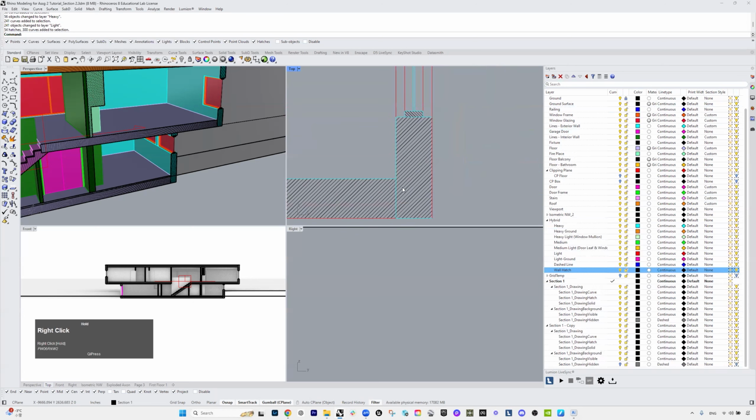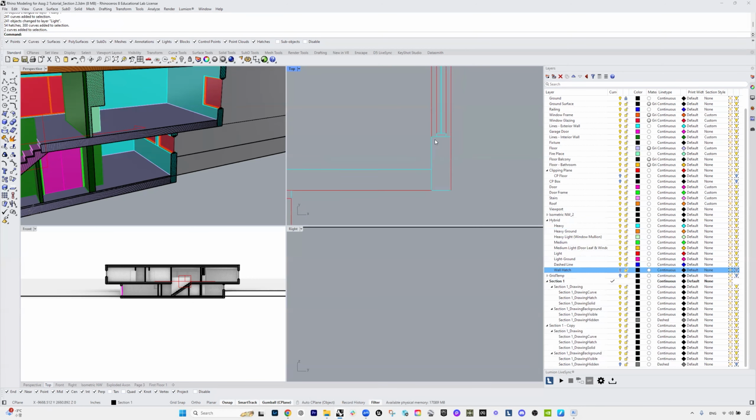Okay, so then in conditions like this, this line is a cut line, a heavy line, but actually I want that heavy line to go over like this. Just like how I did it in the floor plans, I'm going to clean up these sections. Then we can take a look at it afterwards.